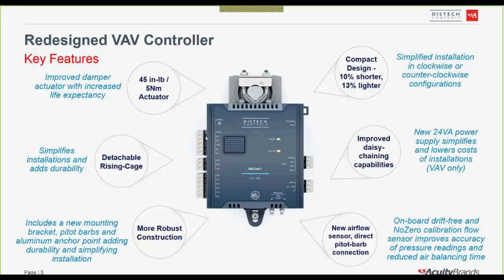Absolutely, Kevin. I really like these new connectors. They pop out quite easily, so it's very simple to do service and maintenance on the VAV controller without having to change your wiring. And at the same time, for those dark ceiling spaces, they are color-coded. So again, a great improvement to ensure that we're wiring the connectors properly. On top of that, on the top right corner of the VAV, we also have a strain relief where we could tie wrap our wiring harness to the actual controller.